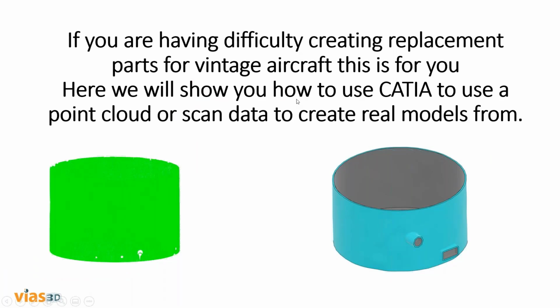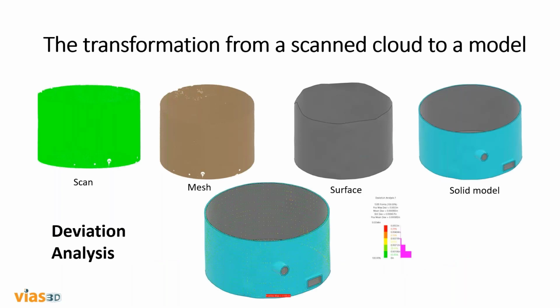Here, if you're having difficulty replacing, and we've seen this in aircraft parts, you would have somebody scan the surface and then use the print to create the part, and then you'd have the surface. And you can line that up that way. Or in this case, this was a fitness for service set of scan points. So somebody scanned a big tank, and then I created a model from it using the print as well. So it matched print data, but you get the real surface.